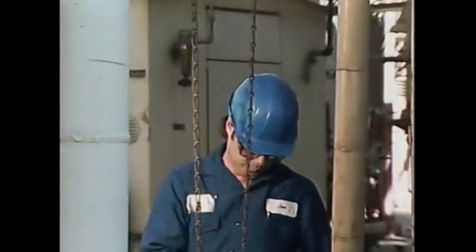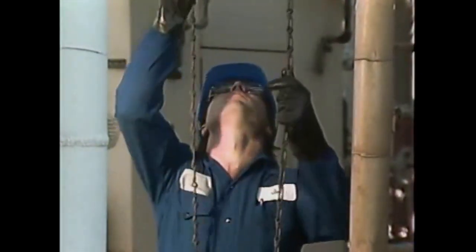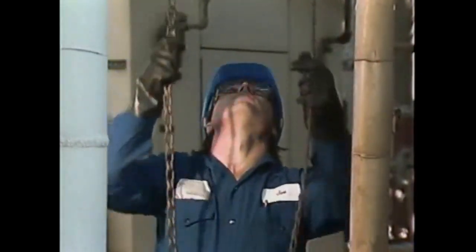When the compressor reaches its minimum operating speed, the gas flow to the compressor can be started. Once the gas flow is started, the compressor can be brought up to operating speed at a rate prescribed by the compressor's operating procedures. Once a compressor has been started and is operating properly, it should be checked routinely to make sure that it continues to work as it should.